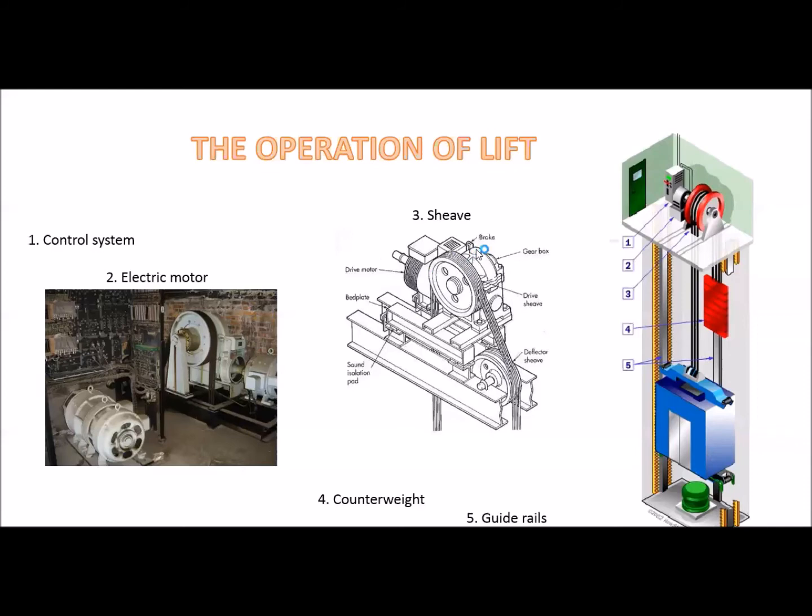The hydraulic fluid in these systems will cut off and the lift automatically releases the brake. The brake over here is the brake that seizes the rope for a complete stop. As you can see here, technically one rope is enough to hold up the car and the counterweight, but the other ropes are just for backup in case one of the ropes is snapped.